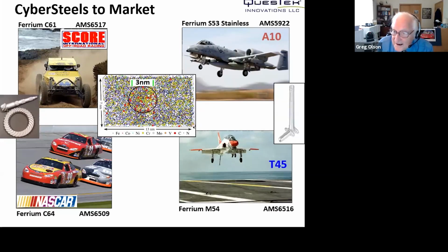And it can actually cause evaporation from the high fields. And so we can evaporate atoms off of the tip and project them to a position-sensitive detector and actually reconstruct the position of the atoms in the tip. So it really is taking us down to nanoscale spatial resolution with detectability of all atoms in the periodic table.